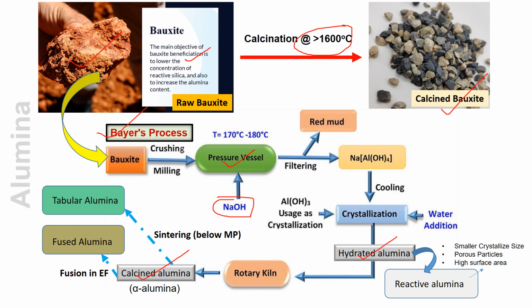The aluminate solution is then decomposed, producing aluminum hydroxide, which is calcined in a rotary kiln to produce alumina. Here red mud forms as a byproduct of this process. During this process, seed induces precipitation of aluminum hydroxide. Crystals usually preferred are known as gibbsite.